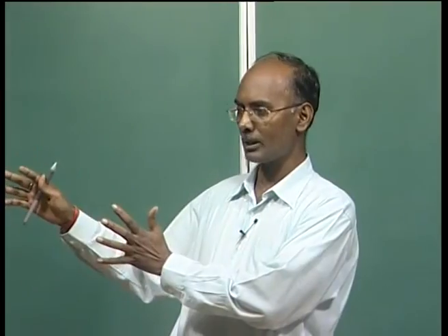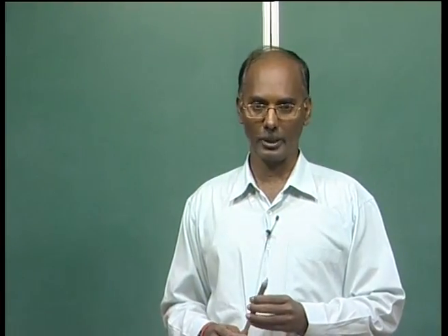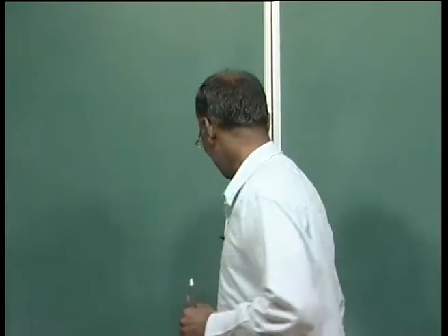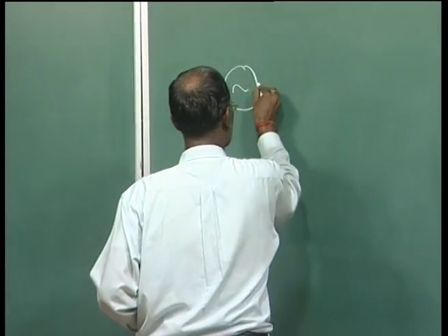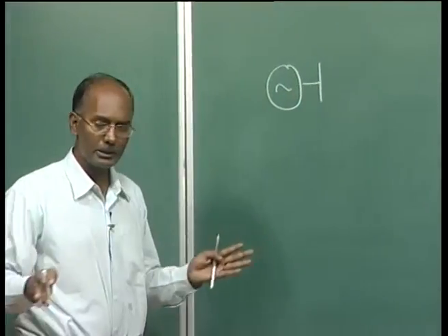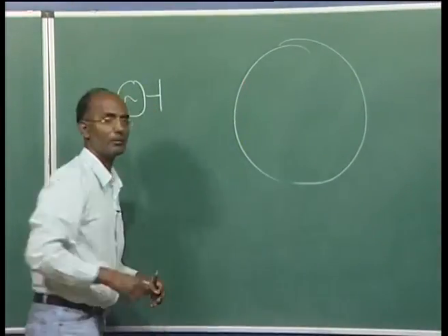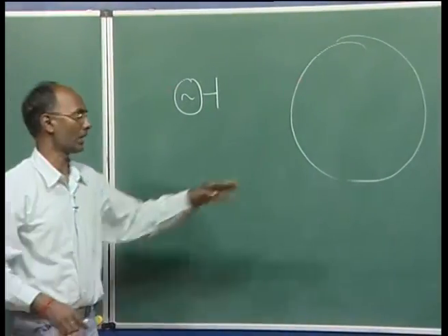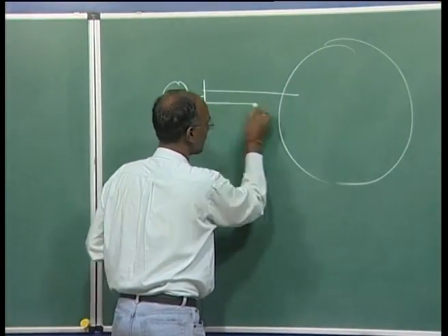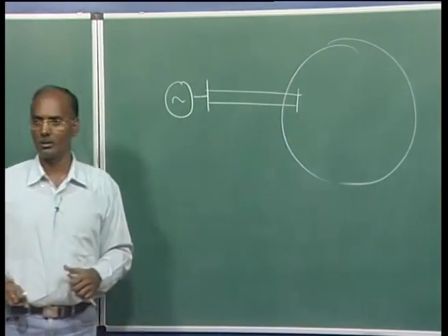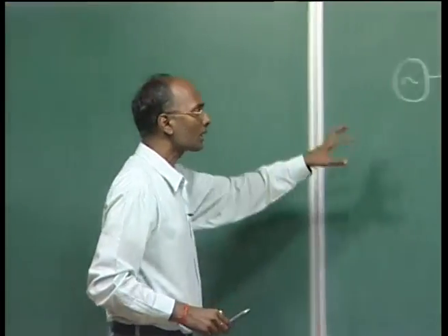Suppose you have this much, x megawatt, then what will be the voltage level and how many transmission lines you are going to have. For example, let us suppose a generating station is decided to be here, and you have a network here, that is your complete network having all AC, DC, and having generators, loads, etc. Normally, we connect it with two parallel lines, because we want to give reliability.